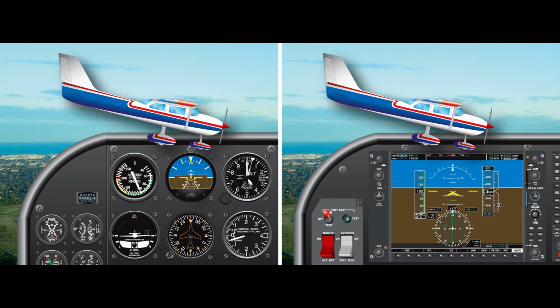A glide is a basic maneuver in which the airplane loses altitude in a controlled descent with little or no engine power. Forward motion is maintained by gravity pulling the airplane along an inclined path, and the descent rate is controlled by the pilot balancing the forces of gravity and lift. To level off from a partial power descent using a 1,000 feet per minute descent rate, the pilot should use 10%, 100 feet in this example, as the distance above the desired level off altitude to begin raising the nose and adding power to stop the descent and maintain airspeed.